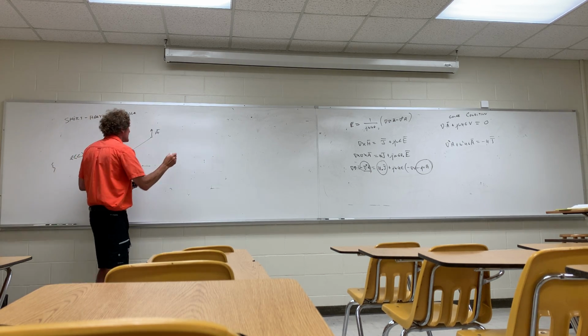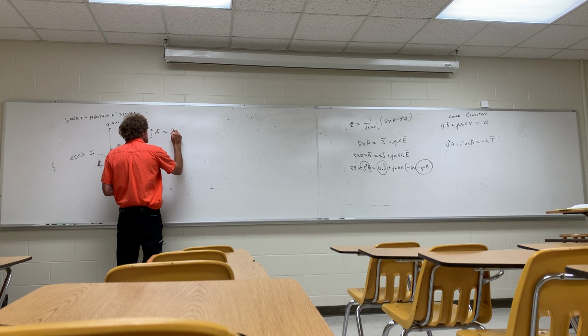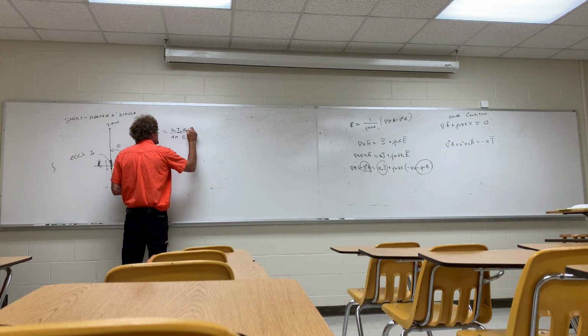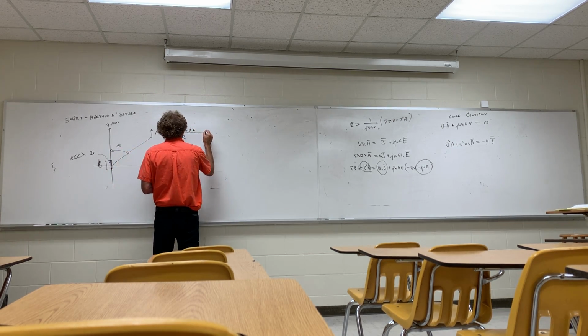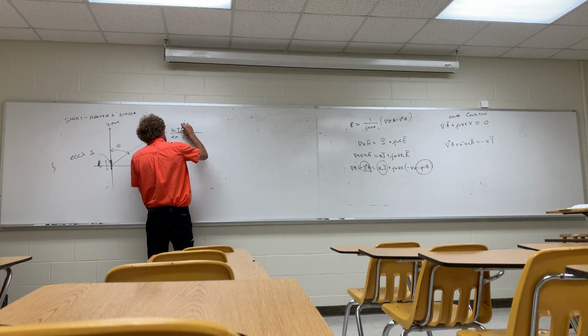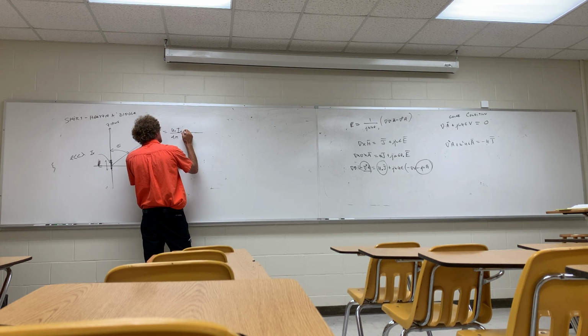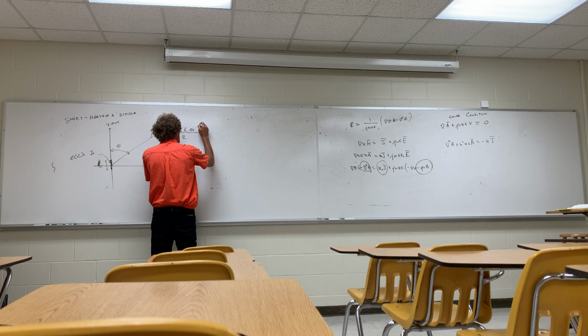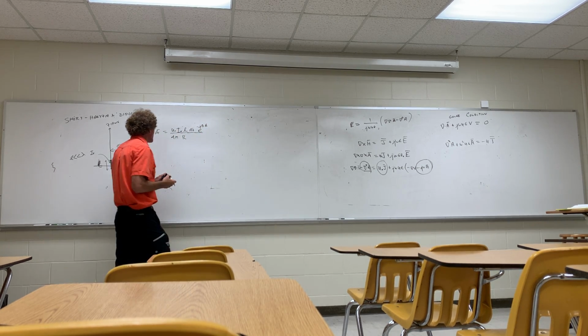A will just be equal to mu0 over 4 pi divided by R times I naught AZ times the length L. Let me do it this way: I naught times L magnitude in the AZ direction, times e to the minus j beta r. At that point, I have A.